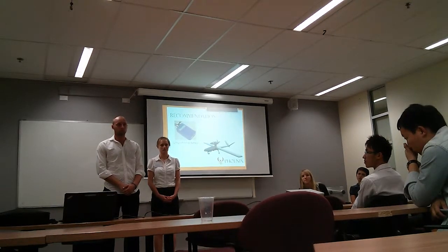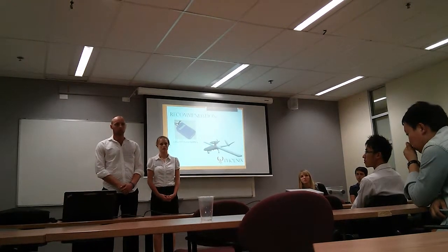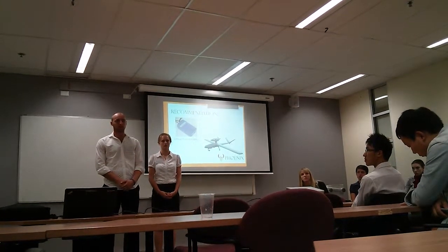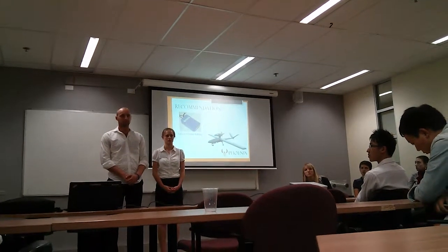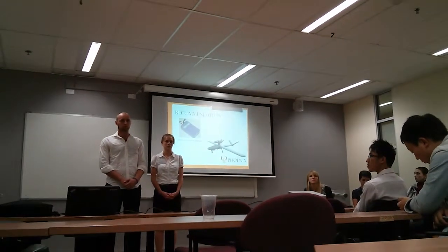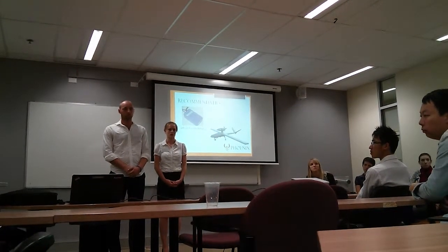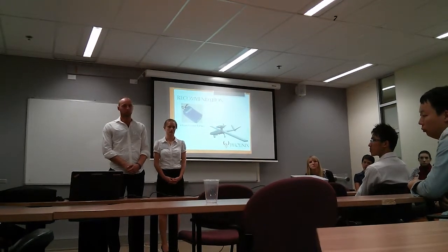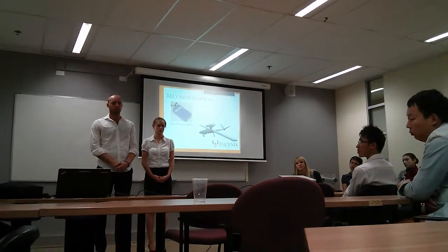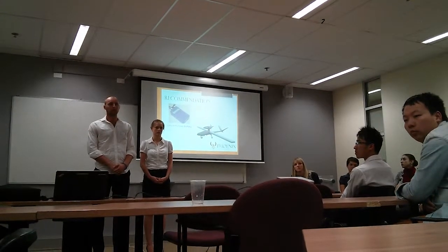Airspeed is the essence of flight, and if this thing's got a 45 knot capability, and all of a sudden it makes a turn and finds itself with a 20 knot tailwind, it's going down. That's it, it's going down. So it needs to know what its airspeed is so it knows what to do about it. It's like a little autopilot. It doesn't need to know its altitude so much, but it certainly needs to know the airspeed. And there's only one way to do that, and that is to have a little tube poking out the front. Even the most sophisticated jets use it. Like a barometer style? Yeah, it's exactly what it is.